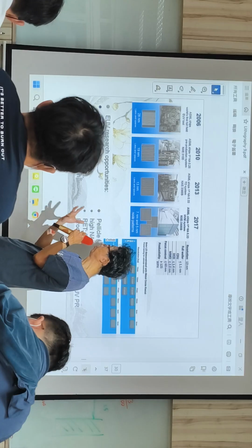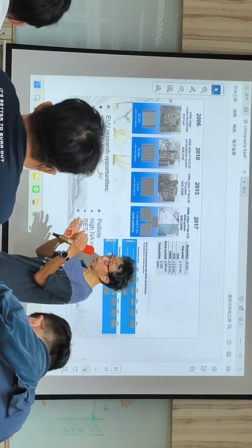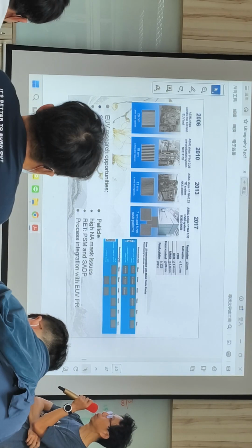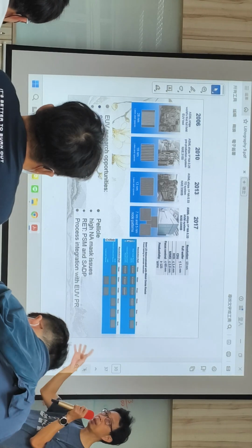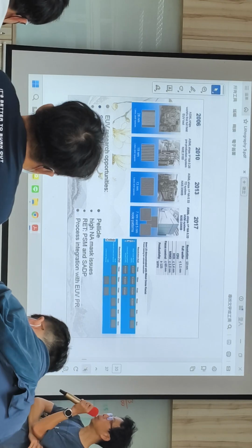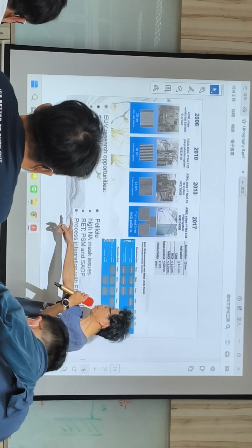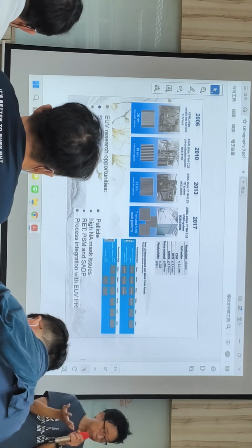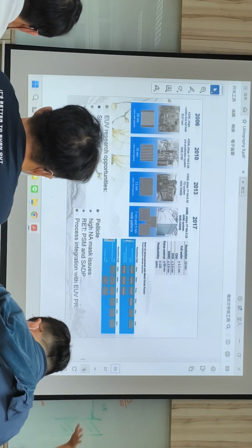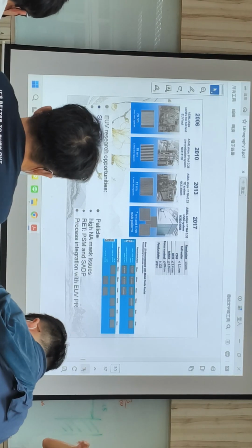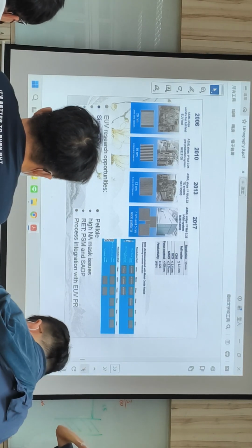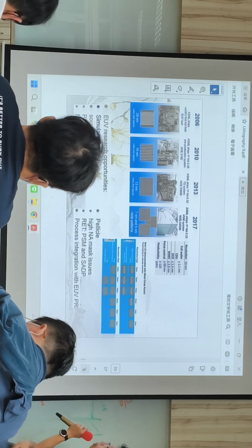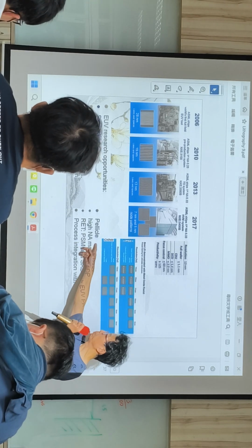If you work with a resist company, the photoresist, how will you be able to handle a nanometer? Are you using silicon containing resist or chemically amplified resist? And then you go back to do the mask inspection. Mask inspection has two areas, like blank. Is there any particle on the blank before you put down the 40 layers of the MoSi? And also, right now, a hot topic is pellicle.